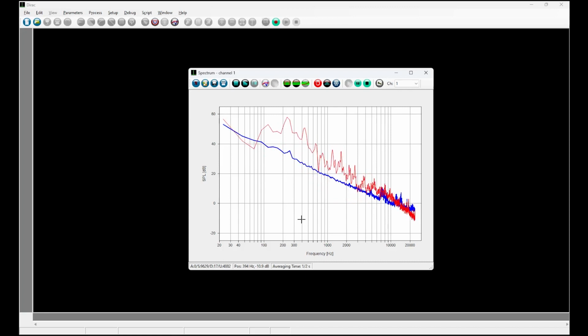In general, even a non-rectangular window will slightly affect the displayed spectrum depending on the signal. Therefore, a window is often chosen either empirically or simply equal to that in previous measurements, for a proper comparison of the results. This brings us to the end of this demonstration. Thanks for watching.